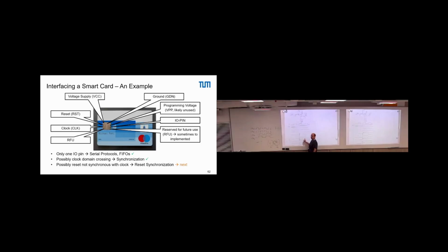partially non-initialized state, right? So we process here data that are not the initial data, and this causes that we start actually out of a state that is not what we want to do, right? So we want to enforce a state where all the O1, O2, O3 initially are 1. That is how we designed the system. But this is not what happens because the reset arrives at some time which does not fit our demands.